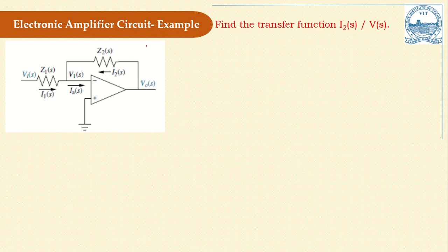Okay, and let us consider another example of an operational amplifier, where I need to find the ratio of V0 of S by Vi of S. The op-amp has a characteristic of gain. For an ideal op-amp, the gain A, the ratio of output voltage to input voltage, is infinite. For a practical case, it is of very high value, which means my Vi, the voltage available at this point, the differential voltage, is nearly equal to 0, and therefore my A is equal to infinite.